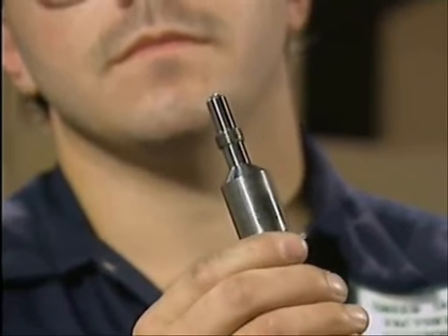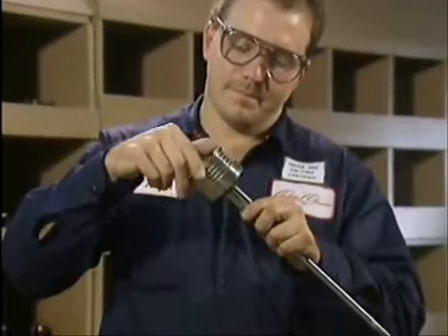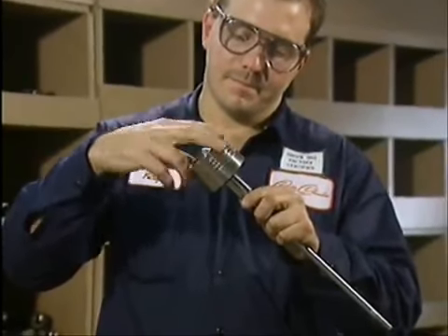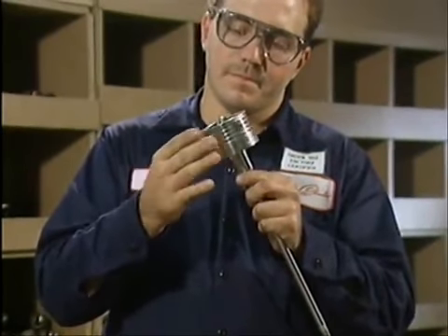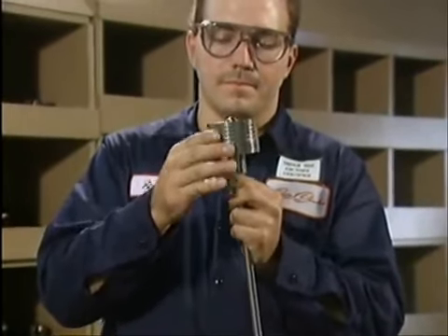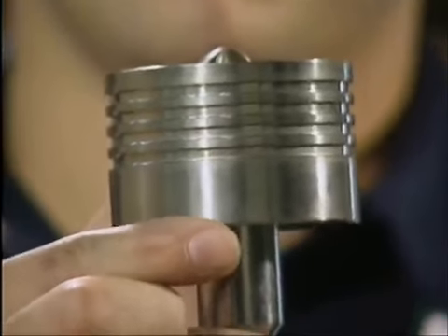Also inspect the valve stem carefully for cracks and other signs of damage. The end of the stem that fits into the disc must be smooth and round, because it acts like a ball and socket joint inside the disc, so that the disc can align itself properly with the valve seat without damaging the stem. Flat spots on the disc end of the stem can cause uneven contact and unwanted friction between the stem and the disc.